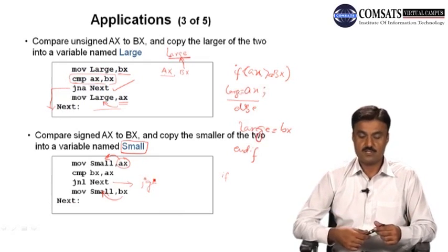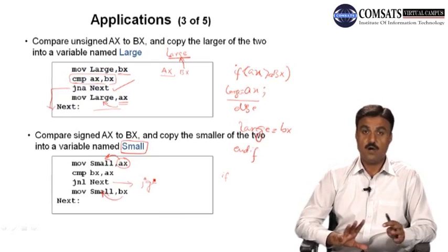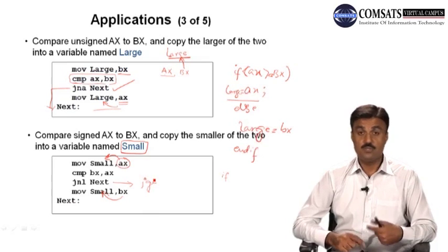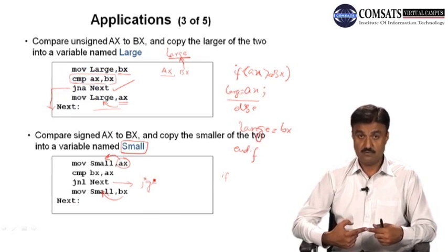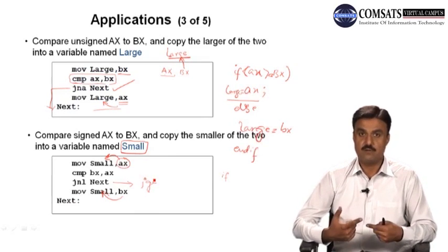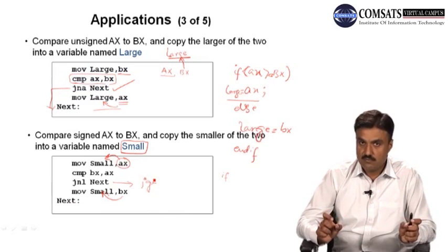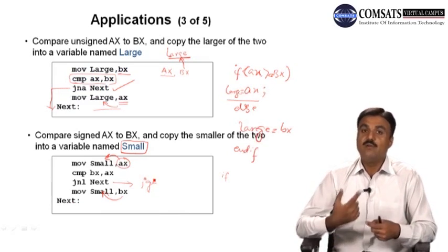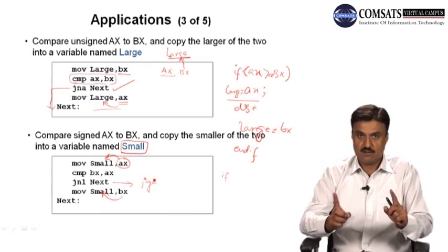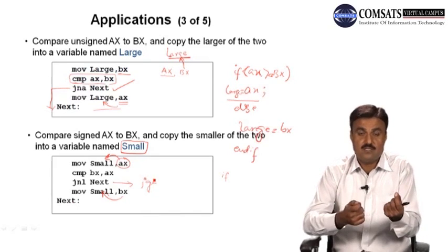Definitely you can use the compare instruction. We know the compare instruction; now the logic depends on how you use it. For example, if we want to create our own loop without using the loop instruction, we assign one register a value of 10, then decrement it, and compare the value, for example whether the register is greater than 0 or less than 0.